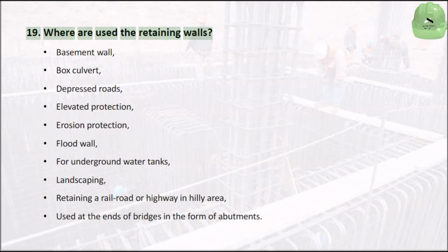Where are retaining walls used? Basement walls, box culverts, depressed roads, elevated protection, erosion protection, flood walls, underground water tanks, landscaping, retaining a railroad or highway in hilly areas, and at the ends of bridges in the form of abutments.